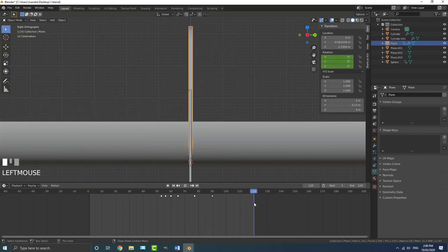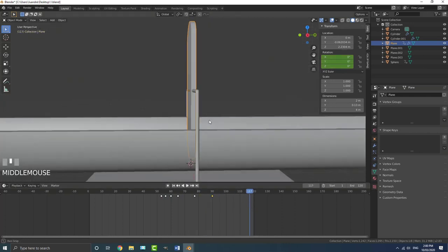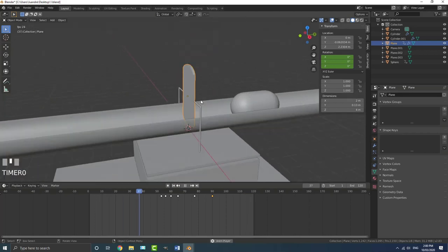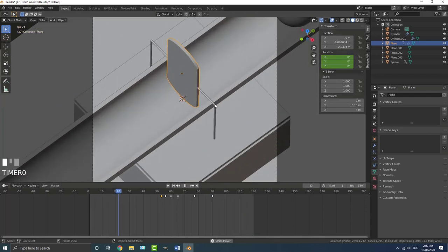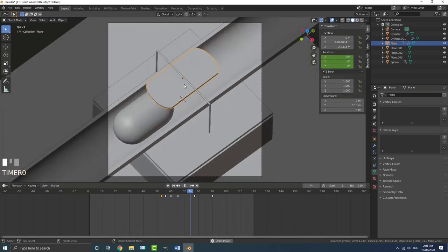So we don't get any kind of weird jumping around when our animation loops. It should just be perfectly where it started at first. So just grab the first keyframe we created, then Shift D, drag it over to your last frame. So it all meshes together. So that is the animation of this scene.